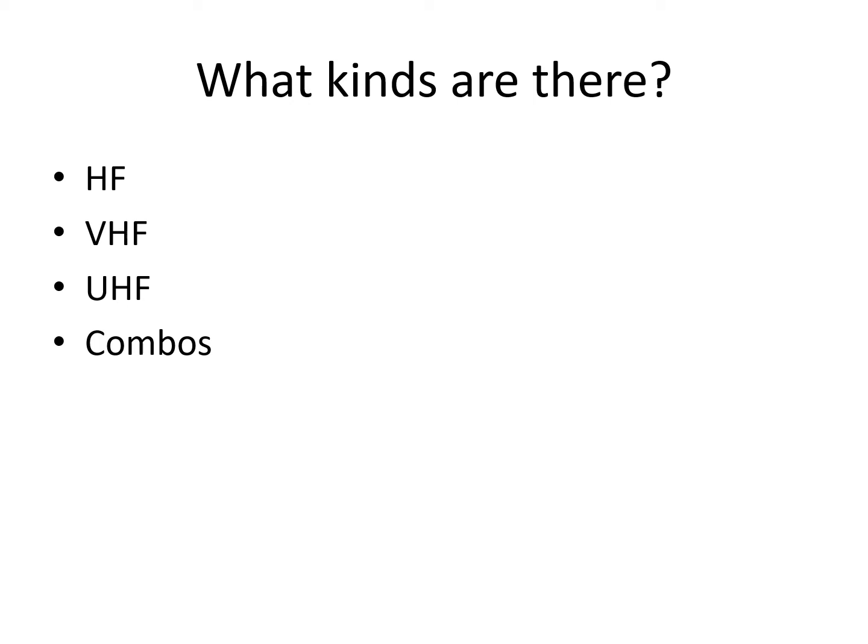The thing you want to be careful of when you select an antenna analyzer is if you select one that's HF only, you're not going to be able to use it on your VHF and UHF FM radios that you might have in your car or in your base station or your HTs. So those are considerations you need to keep an eye out for when you go through your selection process.